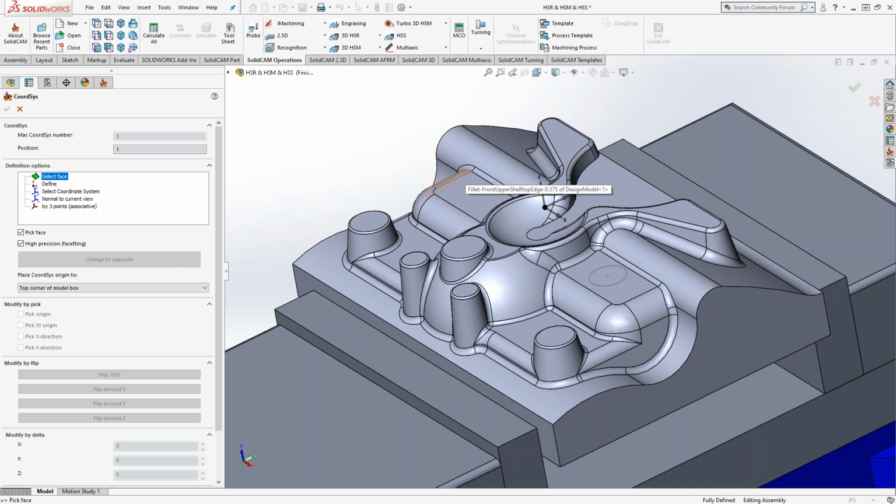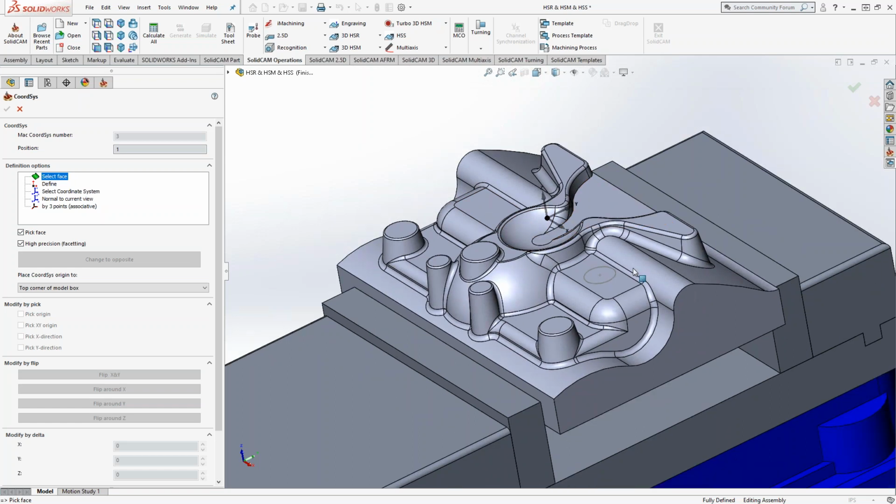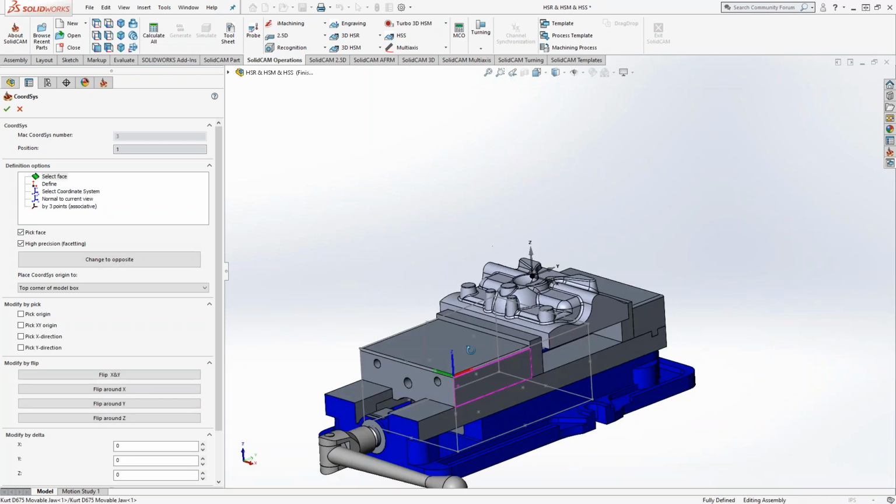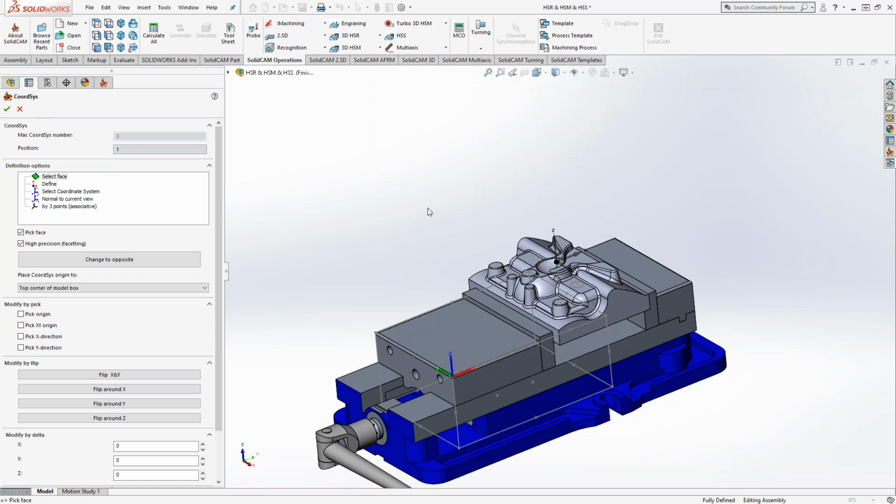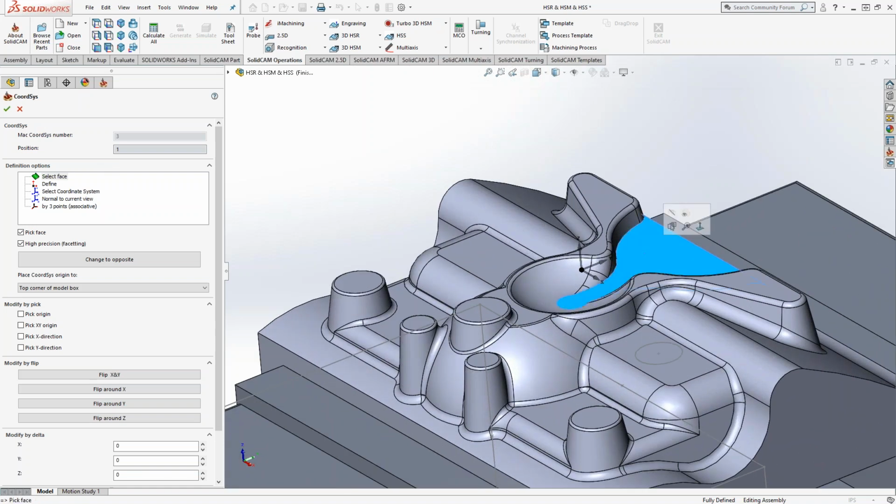And it doesn't necessarily have to be the top face of the part. It could be any horizontal face that orients the tool. Let's say this part here got a lot of curved surfaces on it. It does have a few flat surfaces, but I'm not really looking for those surfaces. Let's say all of these were curved. I can still click on any flat face of any solid on my part just to orient my z-axis. But let's say we do it on the part, just for example. So I'm going to click on this face here,